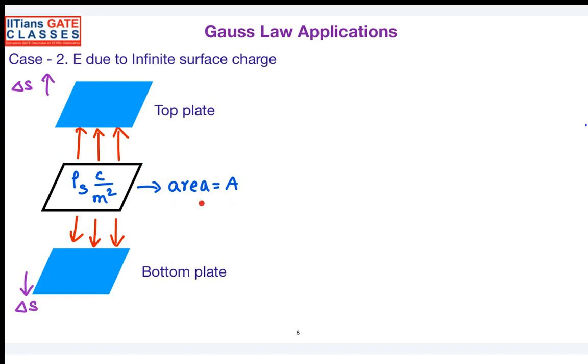Okay, then it's fine. In that case, generally, what is the meaning of a closed surface? In our understanding, a closed surface is something like a sphere or a cuboid, closed on all sides, right? That is physically closed. But here, this configuration is not physically closed, but electrically closed, because the flux is always perpendicular to the sheet.